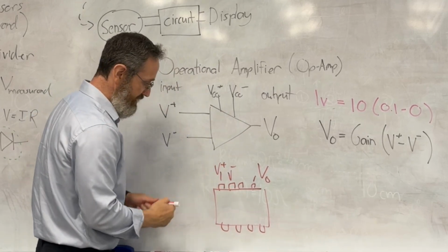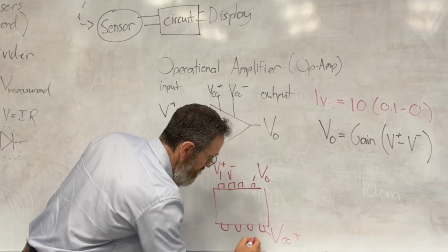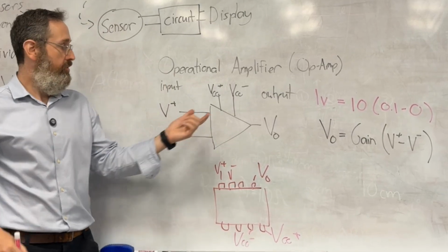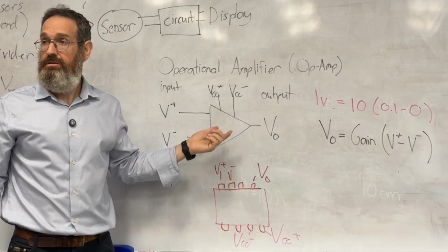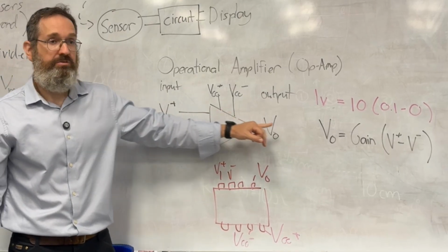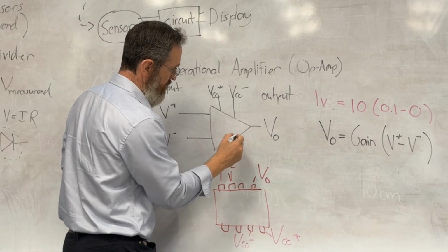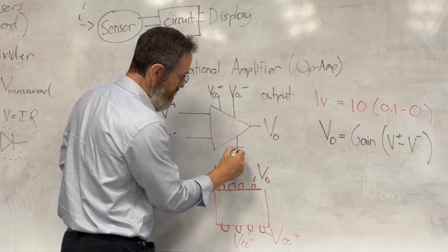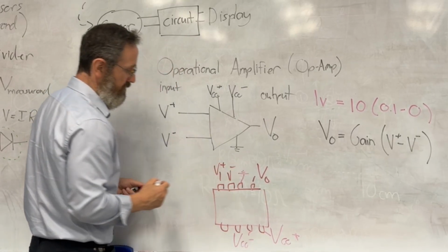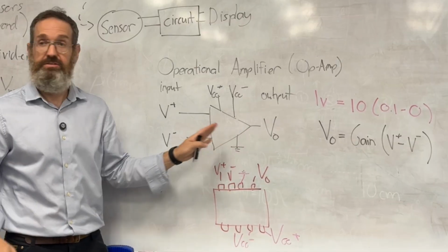So these would also exist somewhere here. Let's say VCC plus might be here, and perhaps VCC minus might be there. So you're connecting your 9-volt battery to the chip. So now we have 1, 2, 3, 4, 5, right? And finally, all these voltages are going to be considered relative to some other point on the chip, and we're going to call that ground. There are variations of this depending on the chip, but this is a good place to start.